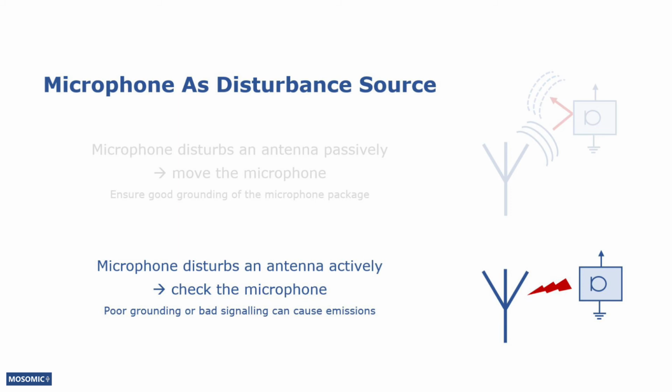If the problem is in the microphone and it cannot be fixed, it's probably best to switch to another microphone model. If that's not possible, the microphone should be moved further from the antenna, or shielding could be put around the microphone.